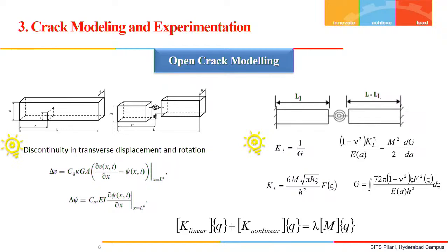Now, the modeling which we have done for the open crack modeling. So basically, this is a beam, and there is a crack. If you talk about the open crack, then this crack will remain open throughout the vibration cycle in the transverse direction. So this crack is modeled as a rotational as well as one extensional spring, and